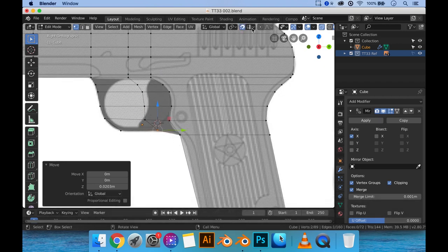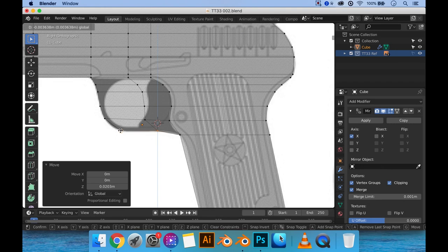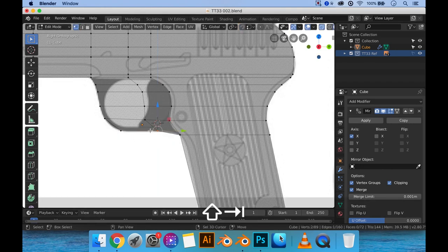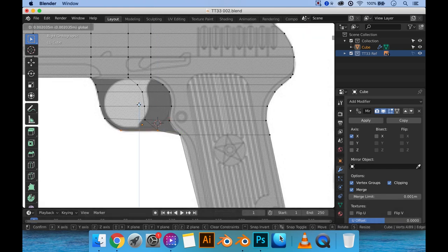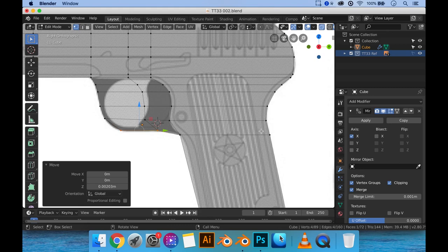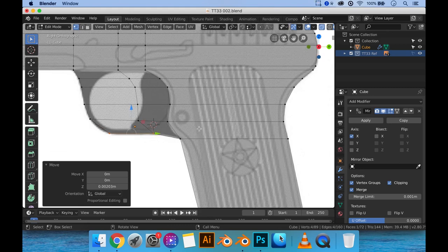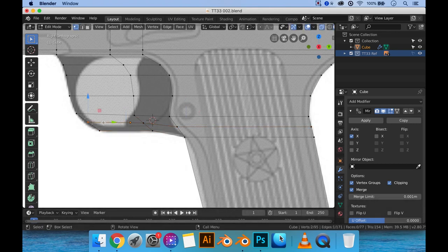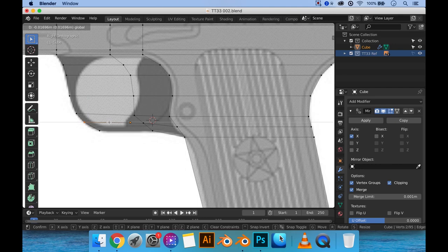Actually, you know what? I turn on snap mode, go into vertex. I wanted to sort of align with this point right here. I'm gonna just hover near it and it should snap over. Turn off snap mode by going Shift Tab, just turn that off. I'm gonna move this slightly up. You can add in additional edge loops over here. You're gonna curve this section, curve this section as well. Just add those. And just push this on the Y-axis right here.